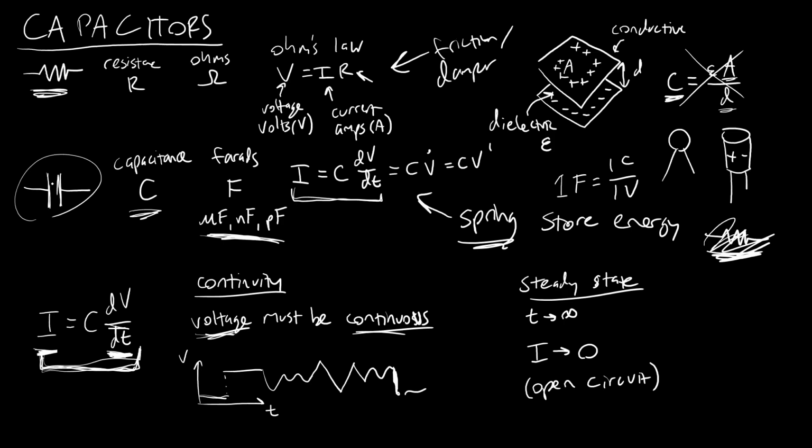And I remember way back in high school physics, this always had me sort of confused looking at this symbol and thinking, well, how can current ever flow through a capacitor if it's blocked and there's an open circuit, right? So if I have an electron coming along and all of a sudden, well, it can't go there because there's no conductor, remember that when an electron shows up on one side of the plate, it can eject an electron on the other side of the plate and attract a positive charge here. So even though it is not literally the same electron traveling across this gap,